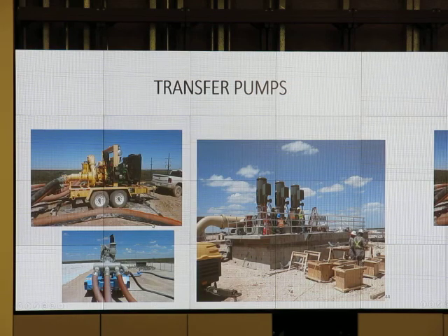The transfer pumps are interesting too. These are large centrifugal pumps. Some of them are mounted on trucks because there's people that'll rent you a pump just to get out of your frac pond over to your frac job wherever you're going. And notice here, this is their suction manifold. They've got 3 probably 12-inch pipes going into a manifold just to feed the suction of a centrifugal pump. Imagine how much water they're moving with that. Because these are diesel engines or gas engines, several hundred horsepower sitting right here.